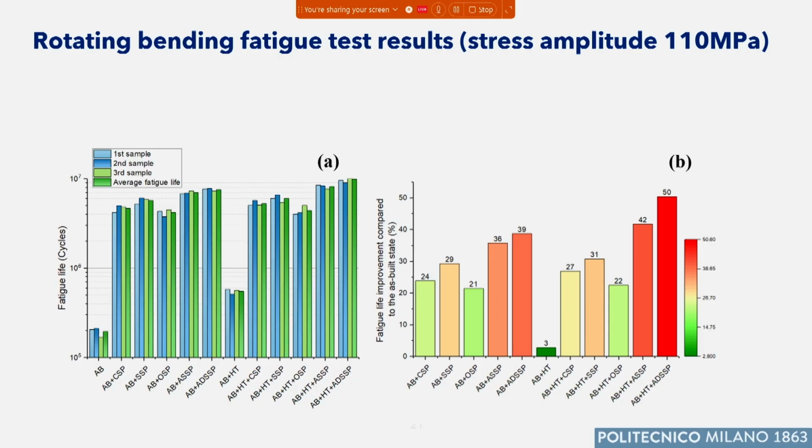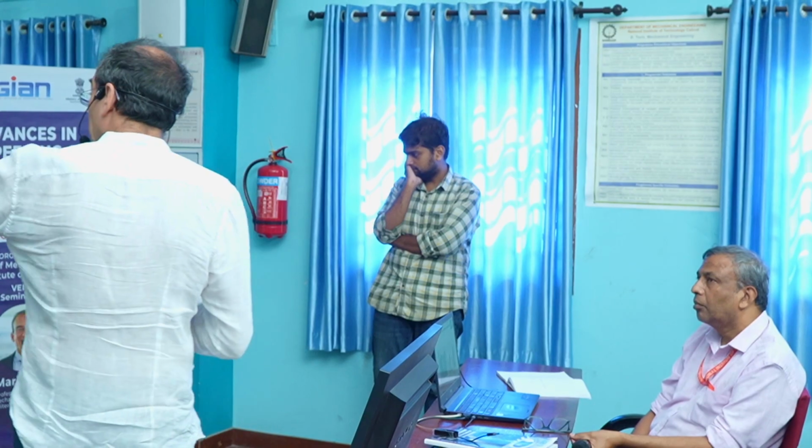In this case, we have not analyzed the problem in detail, but anyway, we think that the reason is that the treatment is reducing the mechanical property, the yield stress and the UTS, but is not able to induce pore closure, or some defect remain, and so the basic microstructure remains the same, in terms of mechanical improvement.